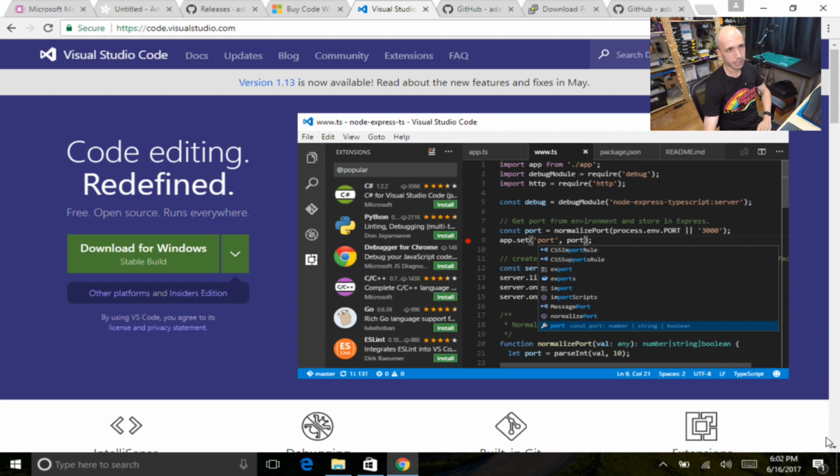But the other thing, like I mentioned, is you can connect to a terminal or a prompt, like a Python prompt on this board, and you can interactively run Python code. It's called a REPL, a read, evaluate, print loop. And you need a tool to access that from Windows, because there's nothing built into Windows that lets you access that REPL on this board. This board is actually showing up as a serial device.